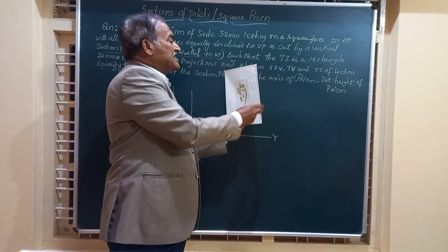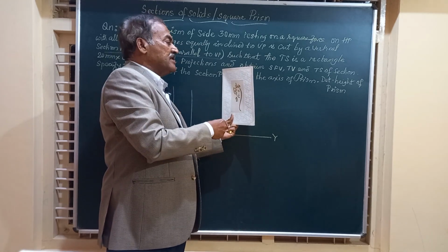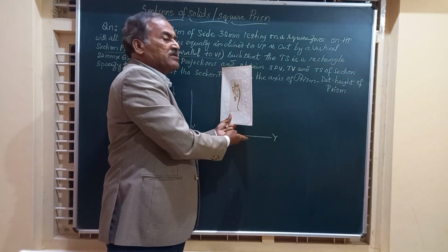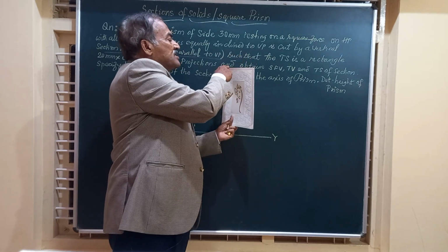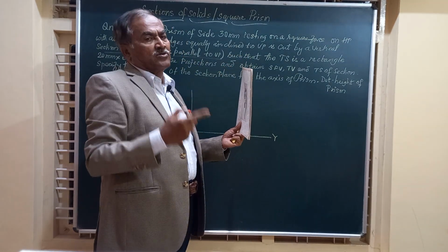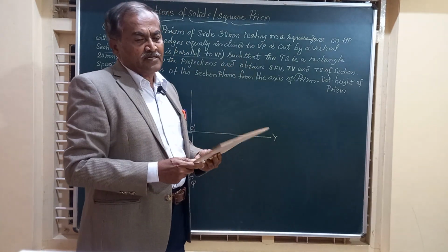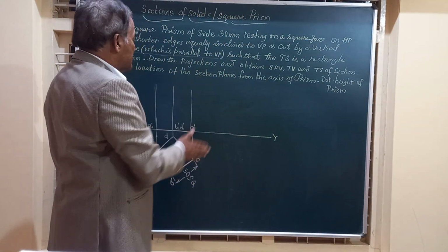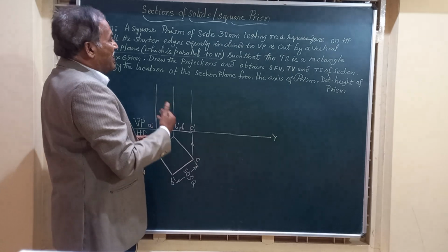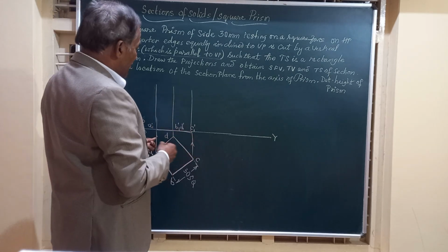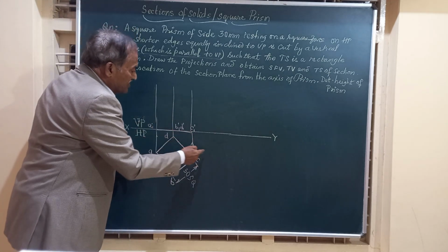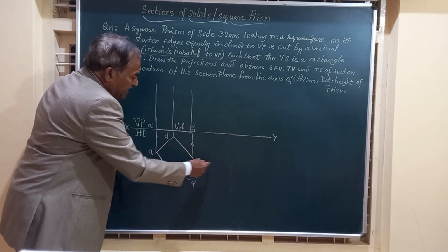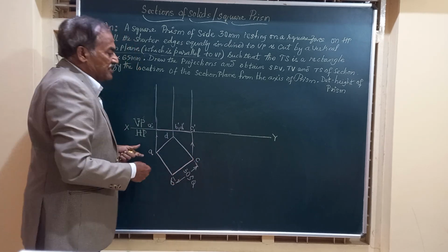But if it is like this at an angle, again, since the surface is perpendicular to HP, you can see this as a line again in the top view. But here he says the object has to be cut by a vertical section plane which is parallel to VP. Parallel to VP means you are going to see the section plane SS as a line somewhere here.